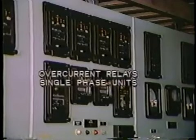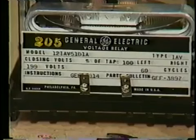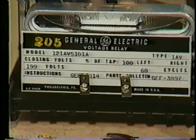Generally, overcurrent relays are constructed as single-phase units, and several relays are required to provide 3-phase and ground protection. The same type of relay with similar characteristics but different wiring is also used for over and under voltage protection.